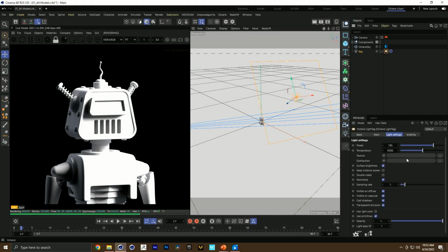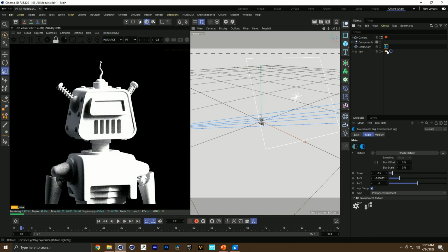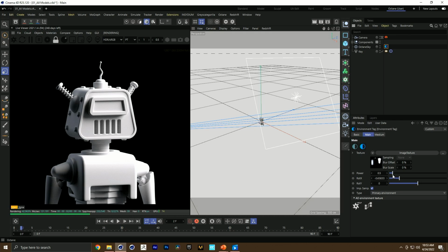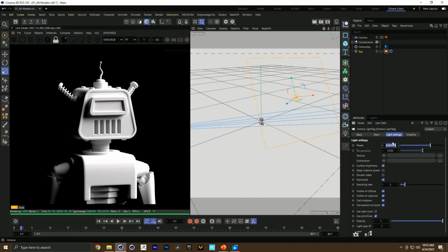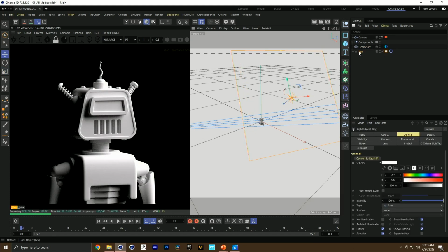So for the key light, I'm just going to have it nice and big to make those soft shadows. Turn it down, probably to around there. When I'm adjusting lighting, sometimes I also turn the other lights completely off so we can just see the influence of this light by itself. So maybe turn that down to like 15, make it a little bit bigger. Okay. And then I'm going to make a copy, holding control, dragging that down. Call this one hair light.